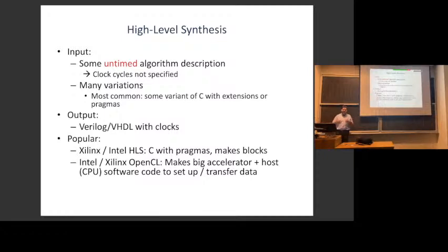And the other thing is, in OpenCL, you don't just write one hardware block. You basically write your whole system. You can write, here are the kernels. The kernels are the parallel parts that in a GPU would run fast, and in a hardware compile will go to hardware. But you also write what's called the host code, which is basically just the serial C that sets everything up.